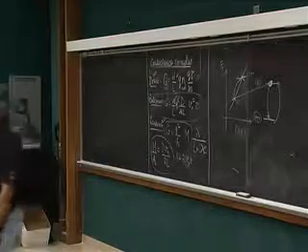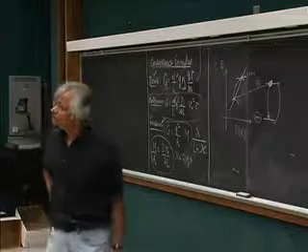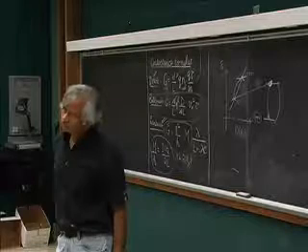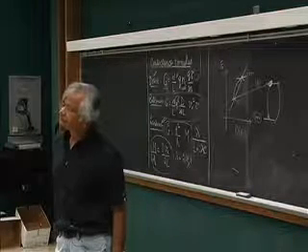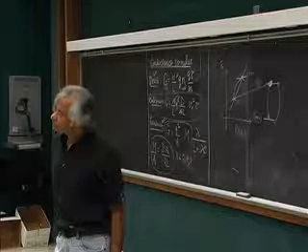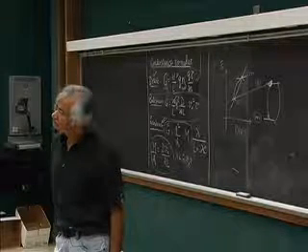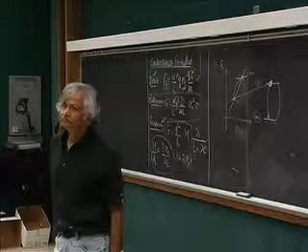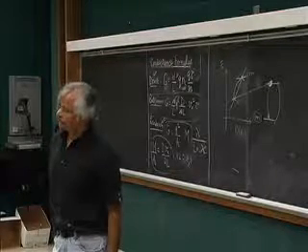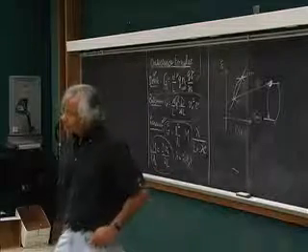When we were using the Landauer formula for ballistic transport, we had the conductance proportional to the number of modes. And when you went from the Landauer formalism to the non-ballistic case, you multiplied that by lambda upon L plus lambda. Even in a ballistic transistor, there is always a probability that you get into the drain and then scatter back. How do you take that into the picture? I see that you have scattering within the channel, but not on the drain side. If scattering is going on at the drain side, what's the probability of that getting back to the source? Is that also incorporated into this lambda upon L plus lambda?